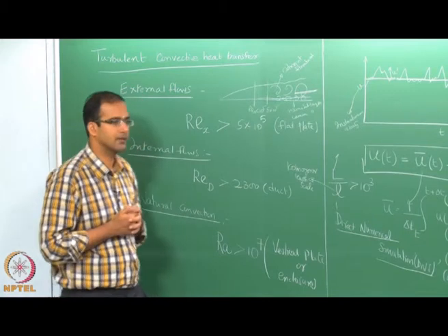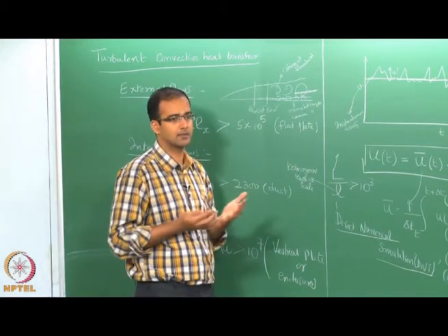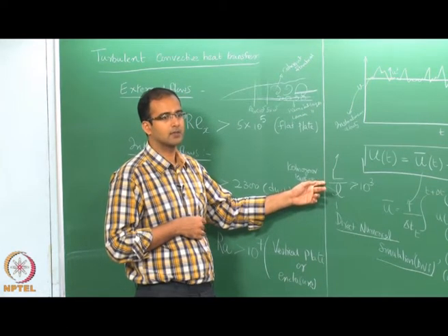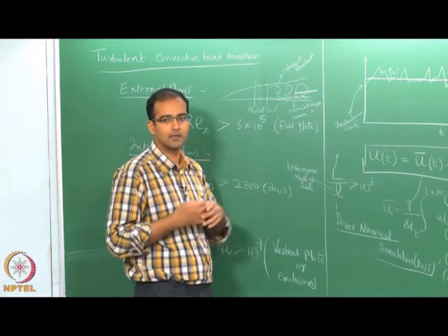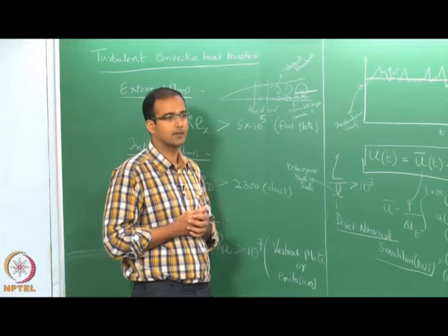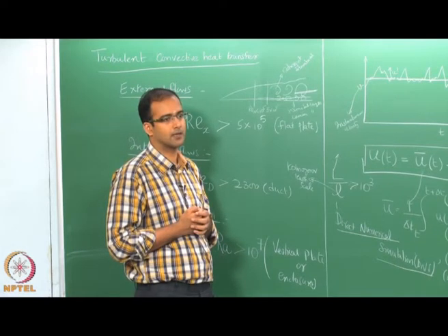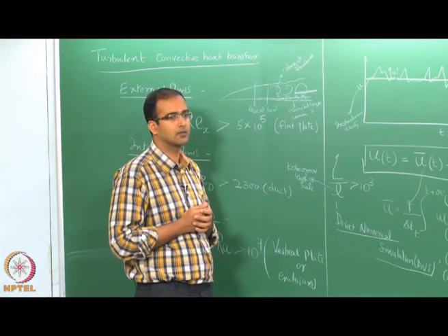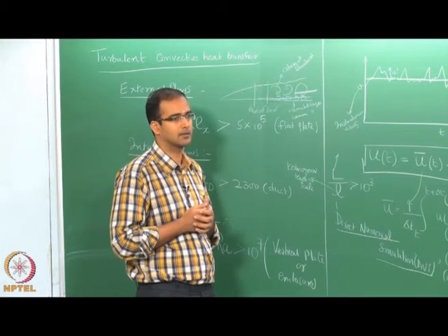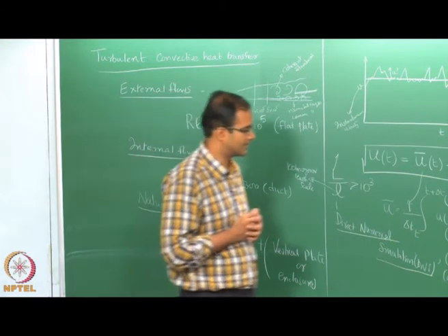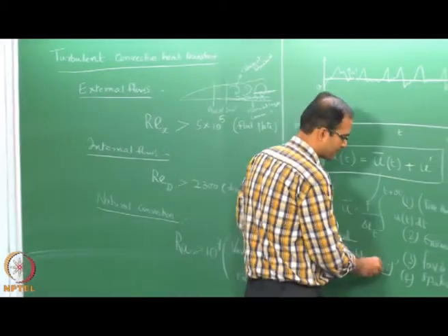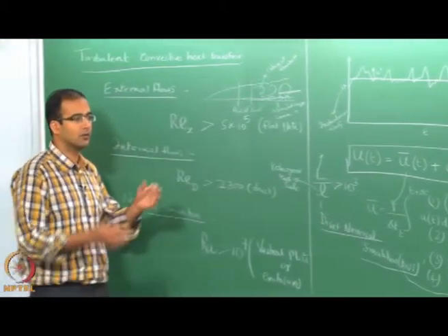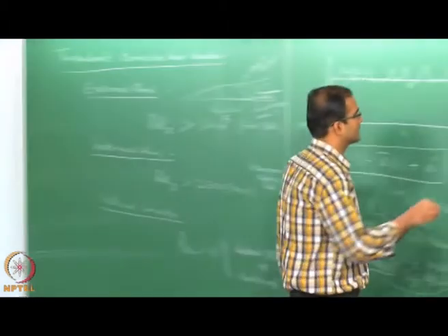Okay. So, this becomes a very challenging task, especially in 3 dimensions. This I am talking about in 1 dimension. Okay. Turbulence is inherently 3 dimensional. So, if you are doing a 3 dimensional simulation, then it will be really a humongous task. You are talking about a mesh size of 1 billion typically. Okay. So, to do even basic turbulent simulations, which will be very computationally challenging. So, therefore, the alternate option is doing some other ways like large eddy simulation, or the more practical method which is called the Reynolds average.